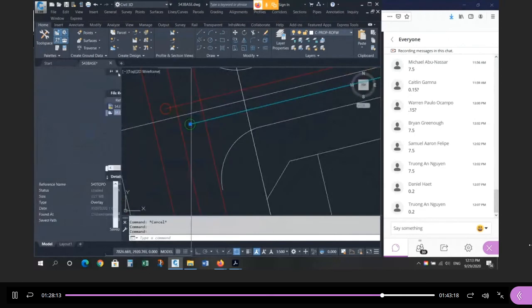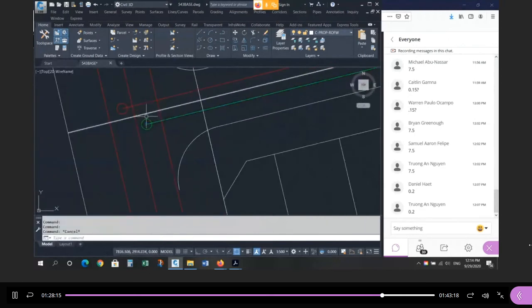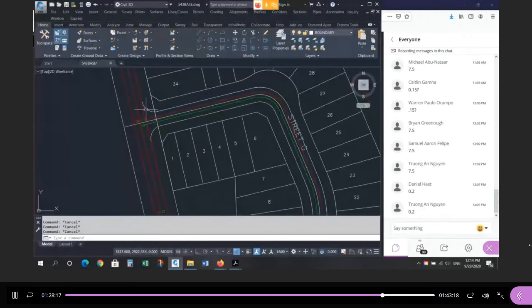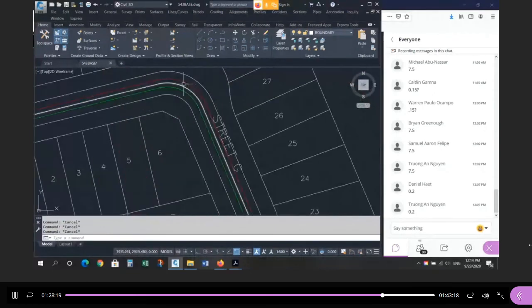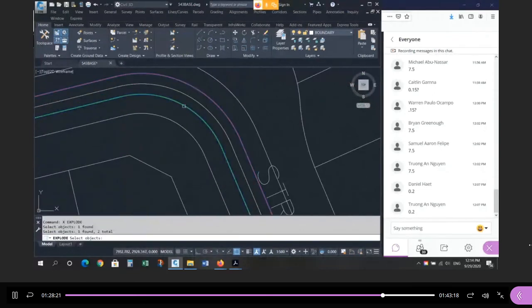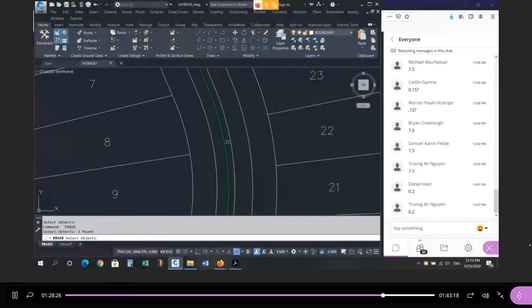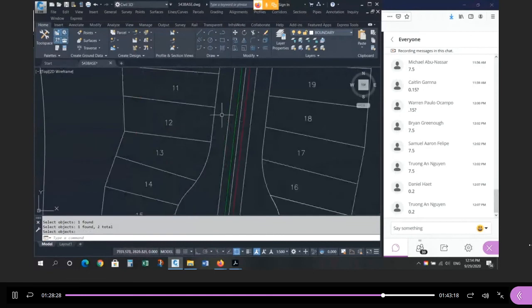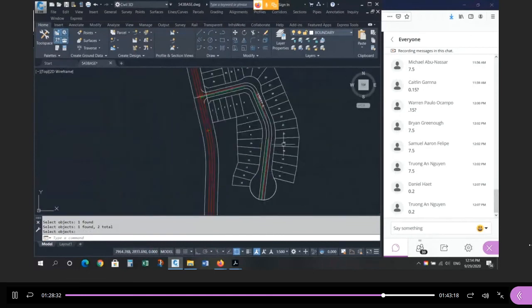And then you can deal with the layers, the actual layer name and color and line type and so on. Okay? So that's generally where the sewer goes. Now the sewers can't be curved, so I'm going to explode those, and I'm going to delete the curves. These curves don't make any sense. You can't curve the sewer, right? But generally speaking, that's where the sewers should go, 1.5 meters either side of center.